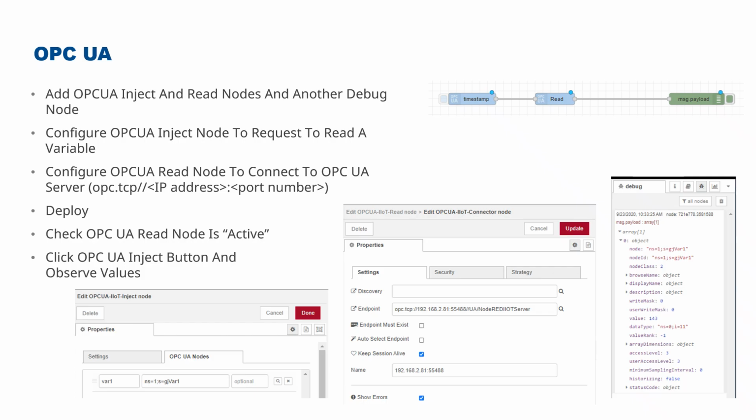And again, with that message payload output device there, you can see on the right hand at the bottom of the screen, this is the output you get from your OPCUA message. Now the key difference between OPCUA and MQTT is that OPCUA includes a lot more context around the information. So you have a node space, you have the actual variable name, you have quality values, and there's quite a bit more potentially in there. It does mean that OPCUA uses a bit more network traffic, but that's normally not that big an issue.